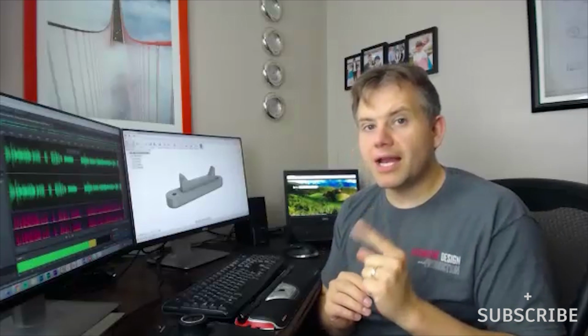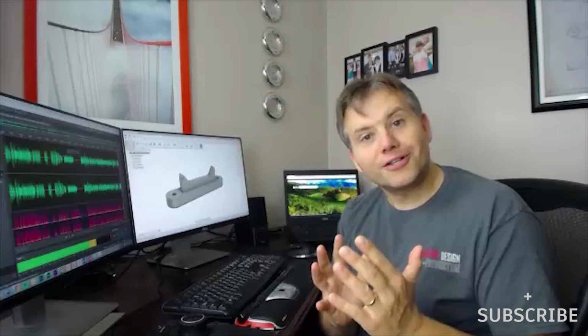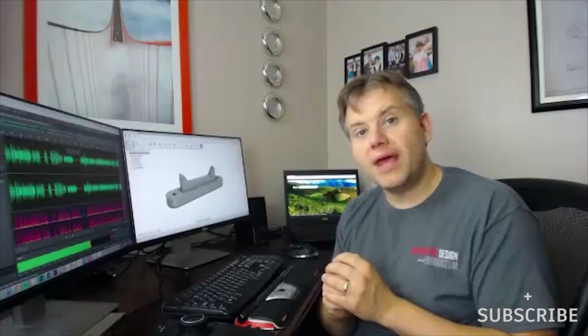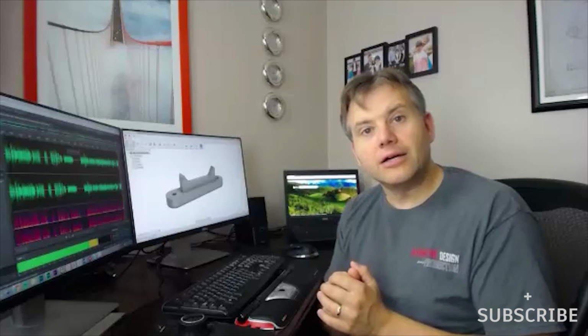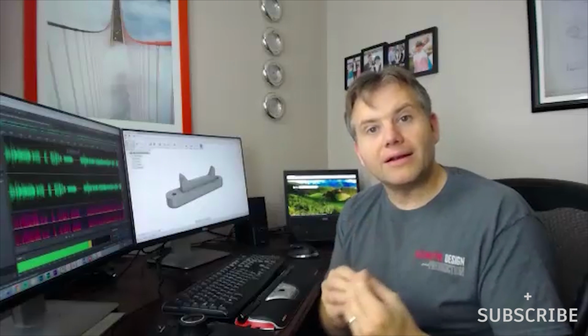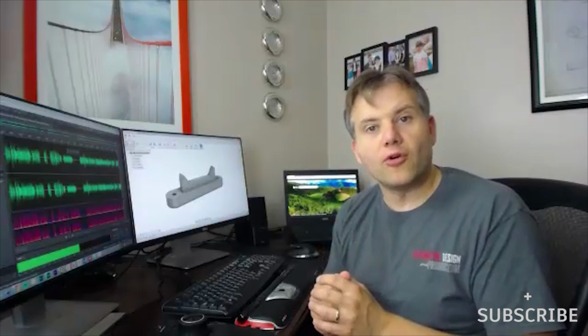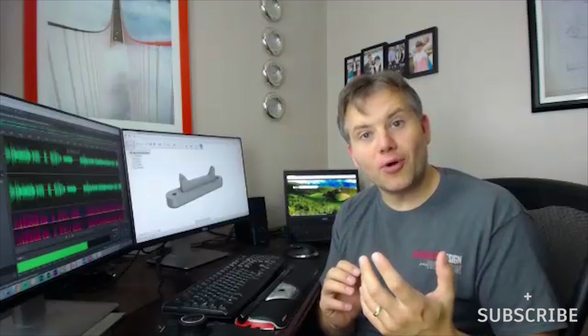Some of the things to keep in mind about STLs is that depending on how fine or how coarse these triangles are, that can really change the shape of your model. So if you make a very fine triangular mesh, which you might think is always a great idea, then you will get a more accurate model. But it's also costing a lot of data, right? It's going to be a big file. And a lot of software have limits, so they can only import like 20,000 triangles before the CAD software says I can't deal with this. The other problem, of course, is if you go too coarse, it can really change the shape of your model.